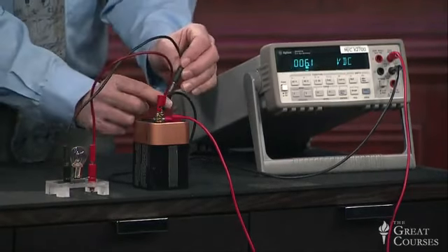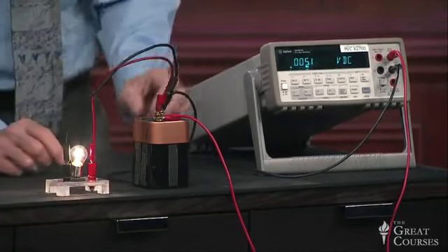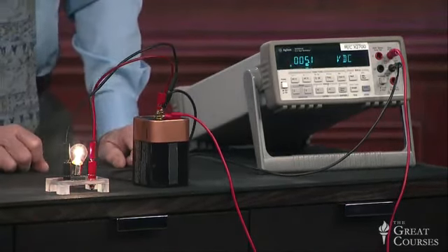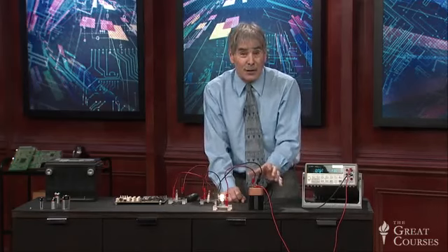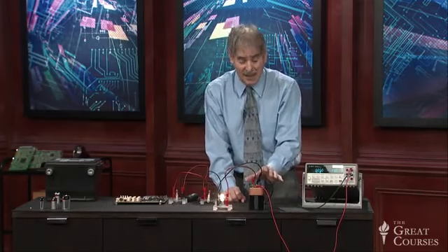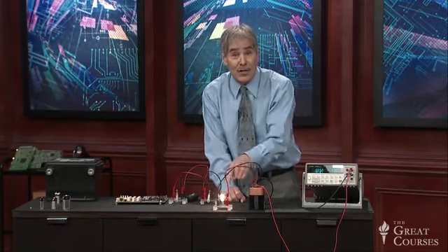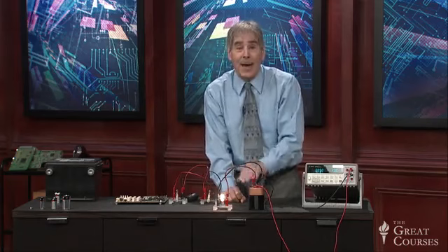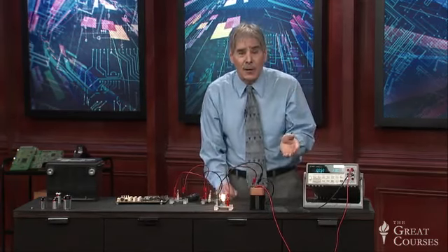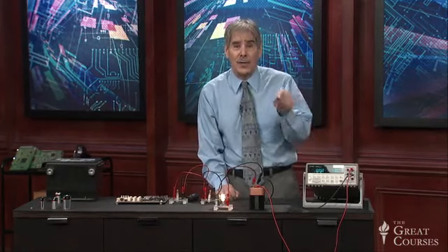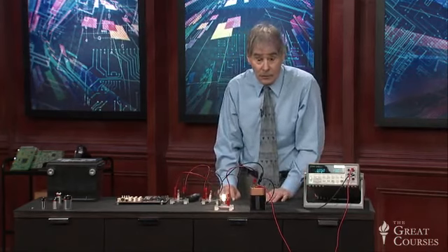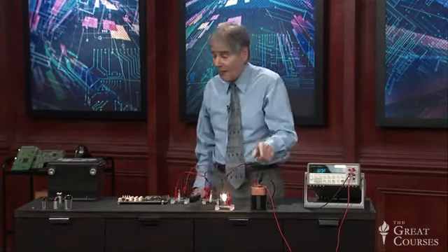And now I'm going to connect the light bulb across it at the same time. And you'll notice the battery voltage has dropped to 5.1 volts. It's dropped by a whole volt. That's an indication that this battery isn't doing too well, or to put it a different way, the internal resistance of this battery is high enough that we can't supply current to this particular light bulb without the battery voltage dropping, because we're losing energy in that internal resistance. Current is flowing through the internal resistance. Ohm's law says there's therefore a voltage across it. And so that battery has too high an internal resistance for that particular application.